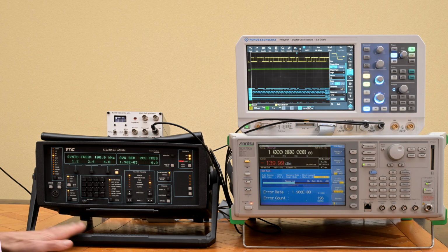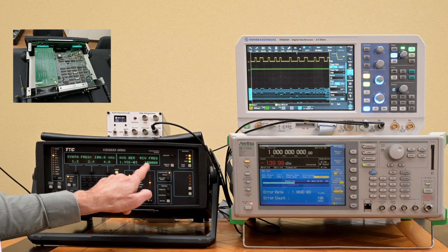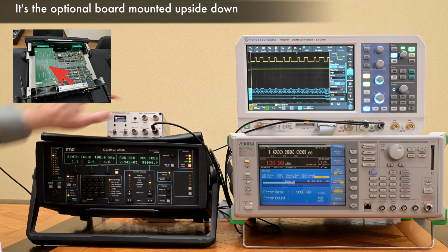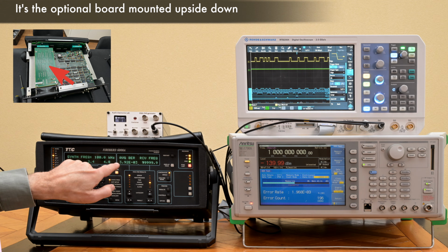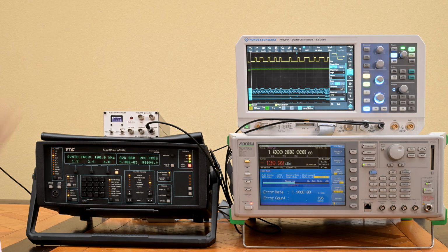Now, what is the special trick that the Fireberd can do? It has a clock recovery mode. So if I go to recovery here, it recovers the 100K frequency from the incoming data signal, and indeed we're seeing the right error rate again. And if I introduce more errors, 294, yeah, 294, 0.391, 391, perfect. So we see that it actually perfectly picks up all the signal generated by my own device, even when the clock is missing.